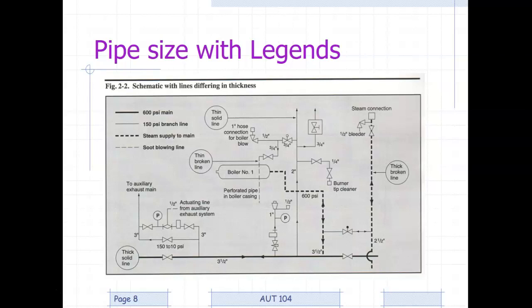Then you have your steam supply line going to your main line, but there is no connection point here in any sort of valve. So I'm guessing it has a small opening there, but I don't think they use the right symbol. But in the case of this particular steam supply line, you see that it has a little horseshoe over the main line. Why? Because it means that it is not what? It's not connected. So basically it's saying, instead of a connection, I've just got two pipes sitting on top of each other, one sitting on top of the other. Okay?